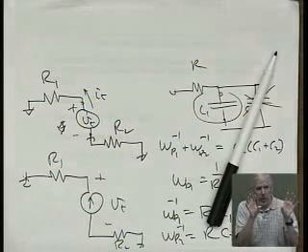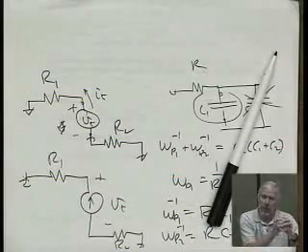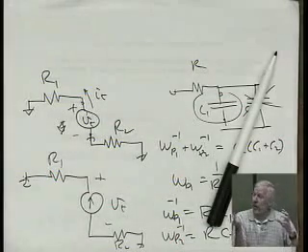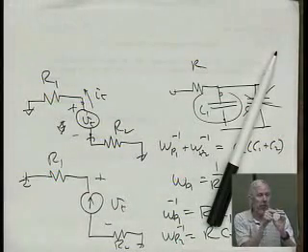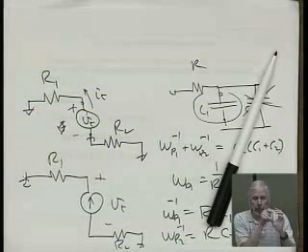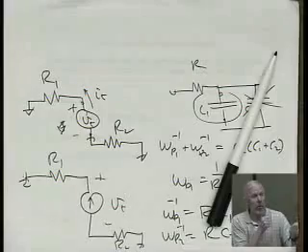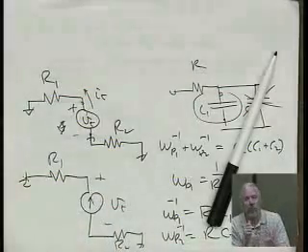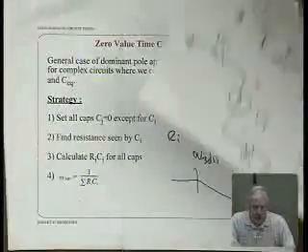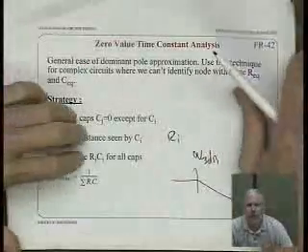You look around and find where the big ones are, and you find this one node is really big. For a design, that's probably where you're going to go after and try to get that node to have a smaller time constant, which means a smaller resistor and a smaller capacitor, both parts of it. Okay, any other questions about that?